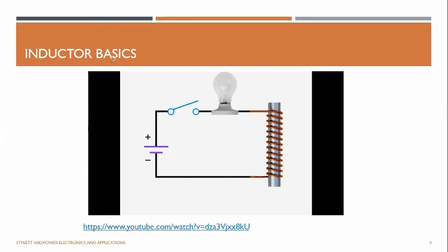You may have seen how this works. When you turn off an inductive circuit, the inductor was carrying some current like this. If you just remove this connection, the inductor current does not change instantaneously, which means it needs a path. That's why there is an arc here.